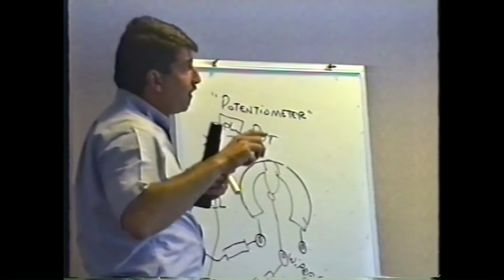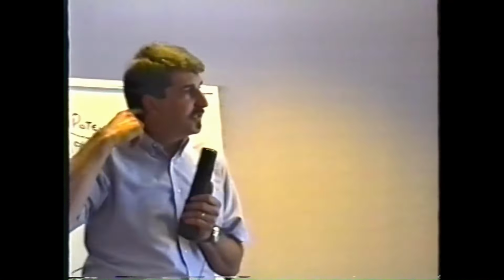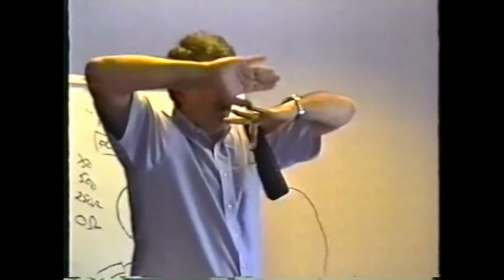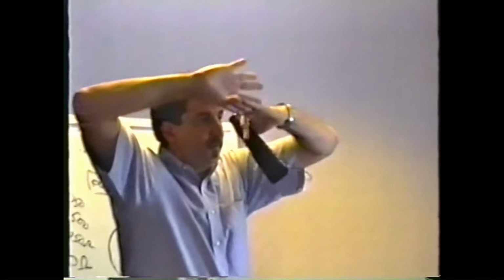But just to give you an example, we had a service call on a monitor, and the service call was that the picture was jumpy. So the service guy went out there, pulls the monitor out, brings it back into the shop, and I plug it in on the bench, and it's jumpy, but I realized that it's not jumping up and down like this. It's getting bigger and smaller. The picture's getting bigger, smaller like this. Big difference between this, which would be the vertical position, and this, which is the vertical size, the height of the picture.